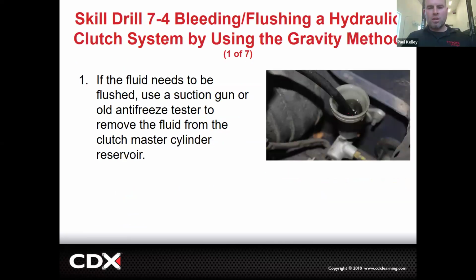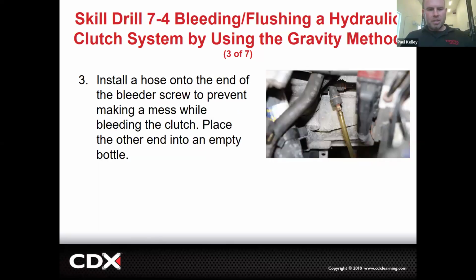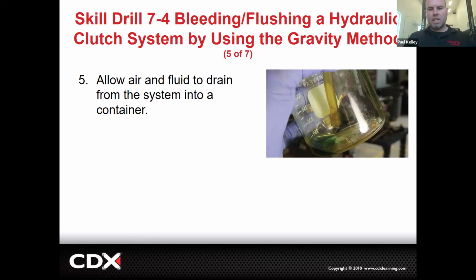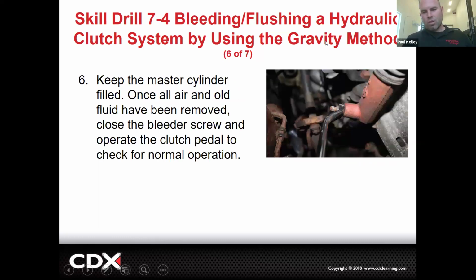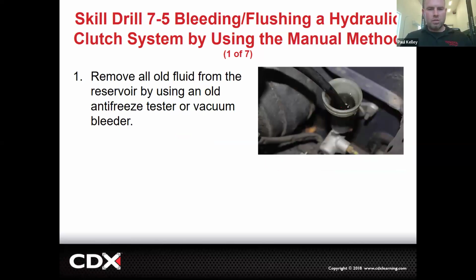Gravity is a little more typical. Going to fill the fluid. Going to go down to the bottom, open up the bleeder, use a hose or use no hose if you want. And then you're just going to basically let it gravity drip, bleed out, and then keep the fluid full the whole time. It's nice when you use the hose dipped into a container because this will make sure there's no way air can ever make its way back up into the system. But with gravity, it shouldn't be real possible. And then when you're done, you're going to snug the bleeder up, set the correct level, don't overfill it. Cool.